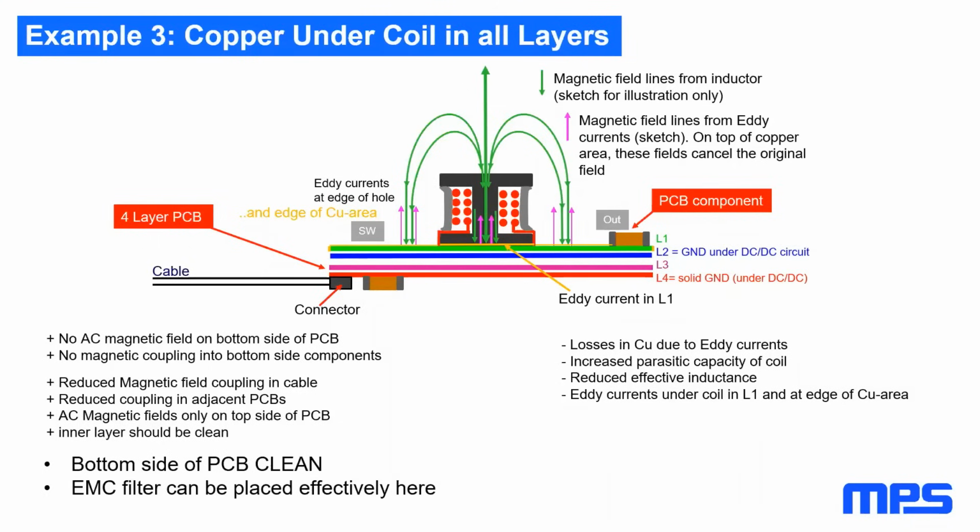So in general, every PCB should have one solid, large ground plane, whole size of the board. That's rule number one. Exceptions to this only if you have very, very good reasons to do this. For example, if you have a very high dI/dt motor drive or whatever, which you can clearly separate also from the steering signals from the rest.